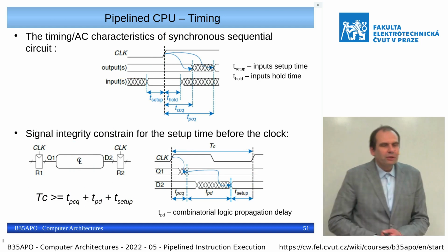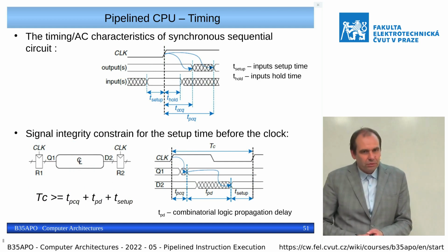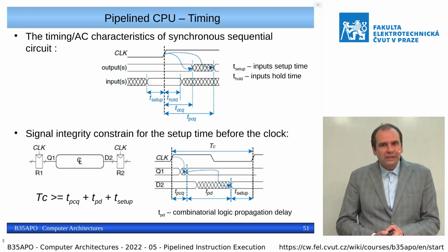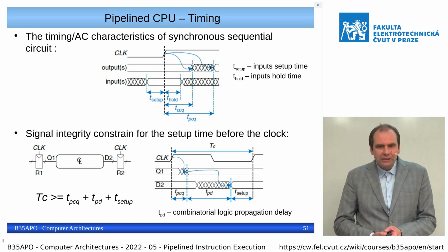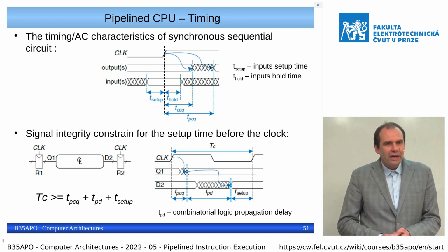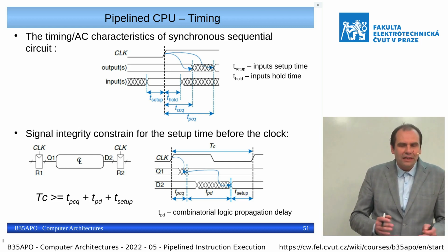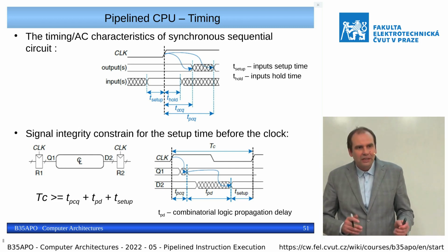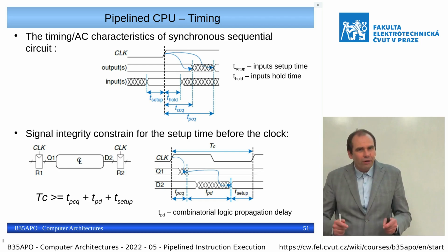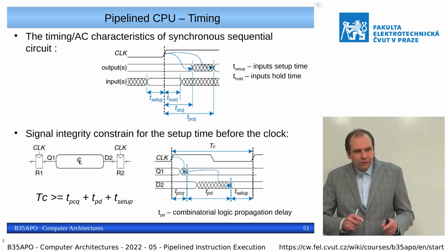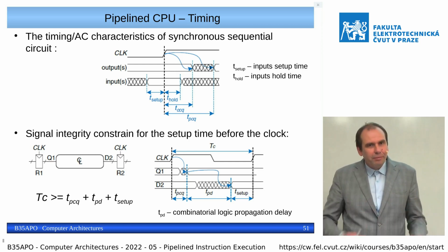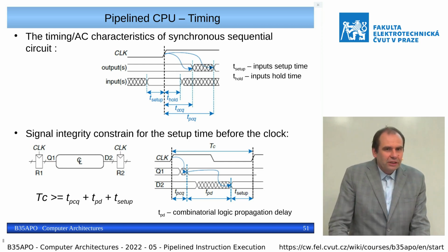It is possible to build an asynchronous CPU which has no clock signal at all. It has been done, but it is very complex because each signal has to add additional logic and signals which inform that the value has already stabilized to the correct value. This way you can build a CPU which has no clock cycle and executes each instruction as fast as possible.